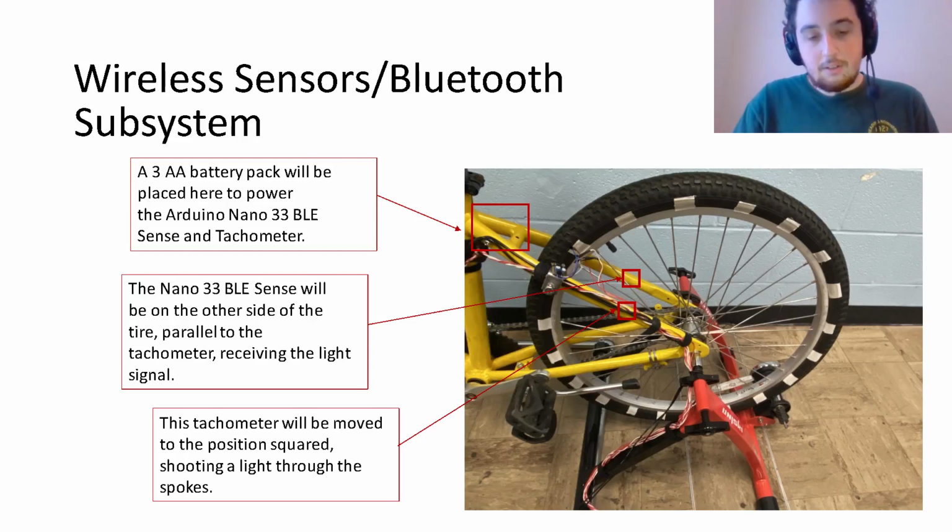Basically, a non-contact tachometer shines a light that hits marks on a moving component like a wheel and can determine the speed from the light hitting these marks. As you can see, the previous team that worked on the Mario Kart bike put pieces of tape around the wheel, and the light from the non-contact tachometer would hit these pieces of tape and then determine the speed from that.